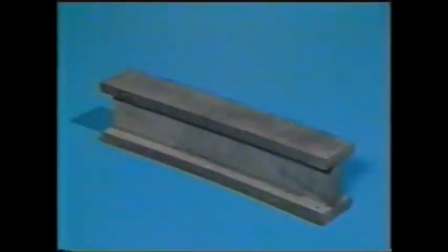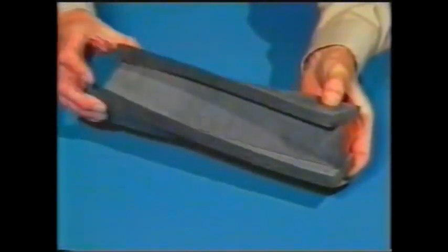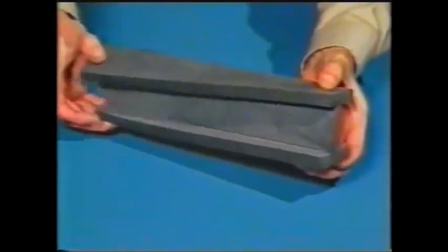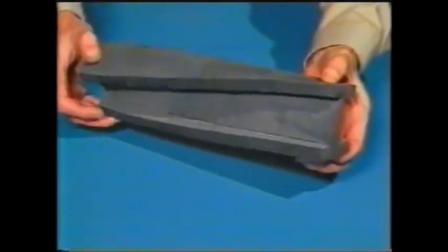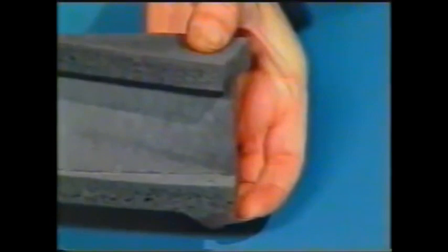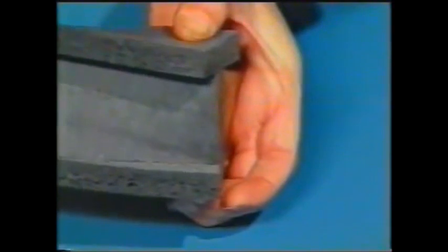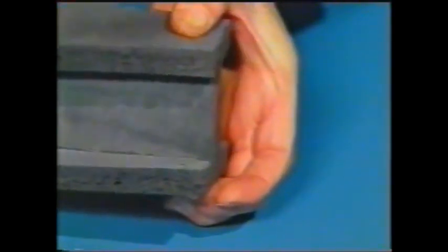There are other actions which are involved in the instability of beams. One of these is warping. For steel beams, actual warping deformations are very small and are barely visible, but they may be seen using the soft rubber model. This short beam is being subject to equal and opposite end couples, and torsion occurs. However, in addition to the primary twisting action, it can be seen that the end cross-sections no longer remain plane, but the elements of the cross-section distort out of the plane perpendicular to the longitudinal axis of the beam. This phenomenon is known as warping.